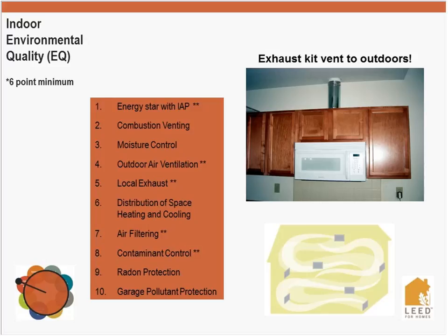If you use the Energy Star Indoor Air Plus program, it would really knock out most of the things you need to do. But we're looking at some simple things like vented and sealed hot water heaters. All sorts of times we see plumbers, even when it's spec'd, showing up with a naturally drafted hot water heater. So you got to watch out for that. And so that's another time when you're doing a rehab, you got to get any old hot water heater or furnace out that's naturally drafted, and you're going to have to replace it with ones that are venting the carbon monoxide outside. We're looking at moisture control, keeping that down.